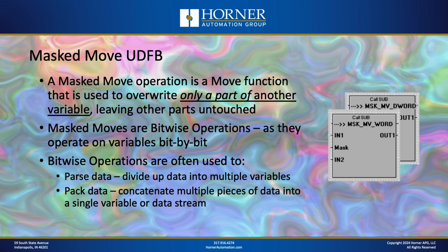Okay, next we have something called a masked move. What is a masked move? Well, a masked move is a special move function. Remember, move functions are where we move data from one variable into another variable. That's a move type instruction. But a masked move is a move instruction where we only move part of the data from a source variable into a destination variable, not the entire thing.